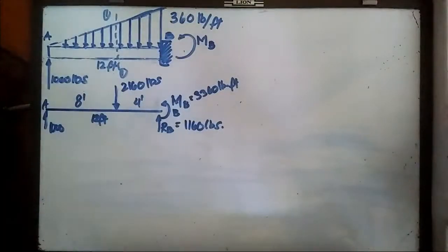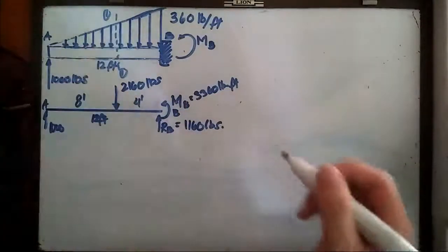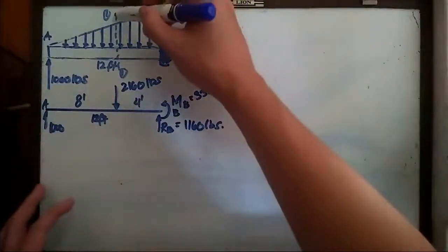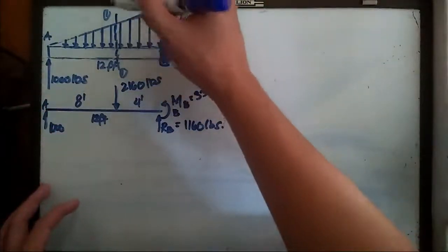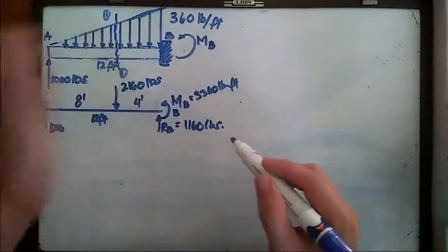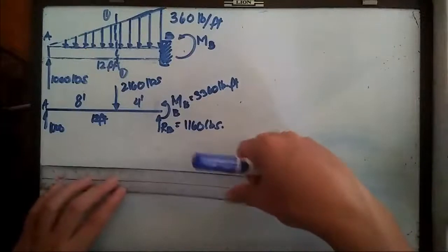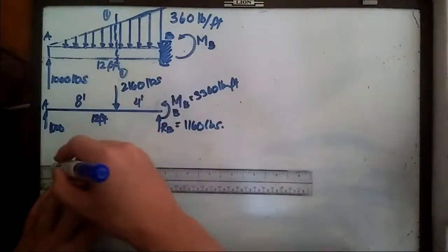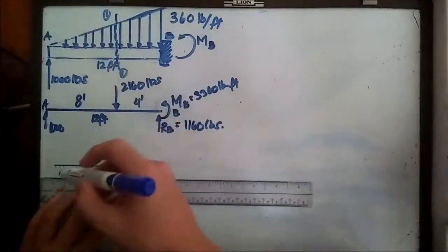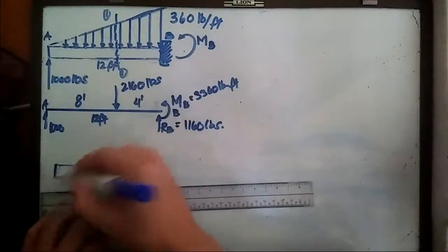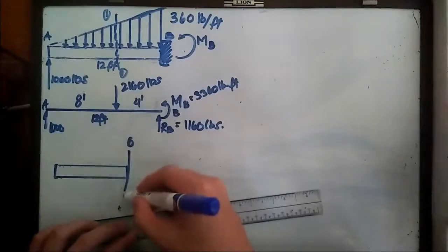Okay, so now we managed to find these two. The next step here is to use either the left or right section of the beam. This is the portion of the beam where I managed to do the sectioning. I'm going to consider the left side. Upon doing that, consolidating the left side of this beam, this is the free body diagram, going like this. This is section 1-1.